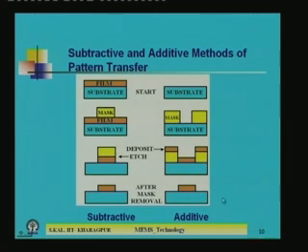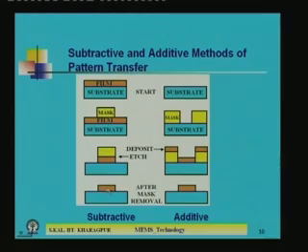So, this lift-off technique is used in some cases where the etching solution is not known, or you know the etching solution, but that etching solution will react with the photoresist film. If that etching solution reacts with the photoresist film, in that case also photoresist will not protect the surface. When you are going to etch the film, photoresist will be reacted and film also will be reacted, then the whole thing is washed away. So, here you need some solution which can dissolve the photoresist, but not the film.